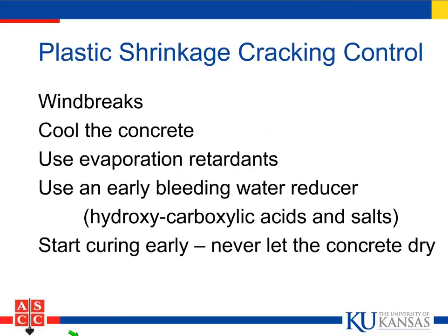So what can you do about plastic shrinkage cracking? Well, you can put up something. You can reduce the wind by using windbreaks. Cool the concrete. That's always good for many reasons. Cool concrete doesn't set up nearly as fast, even in hot weather.